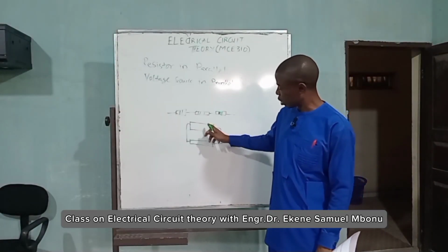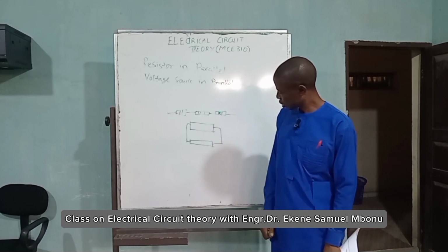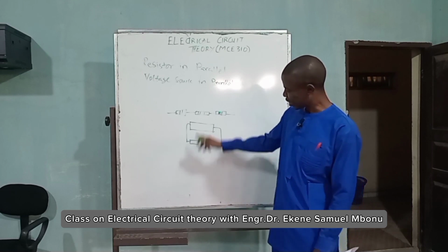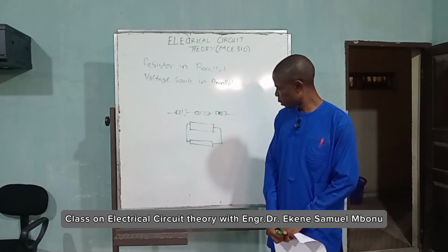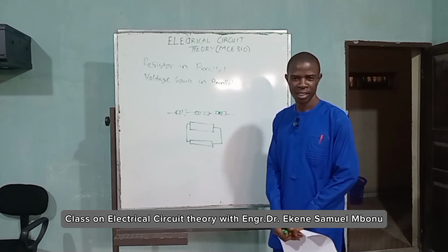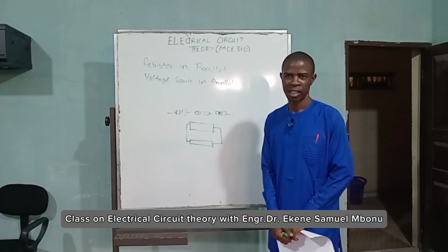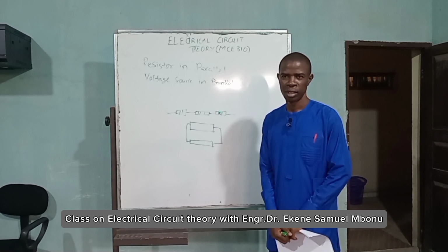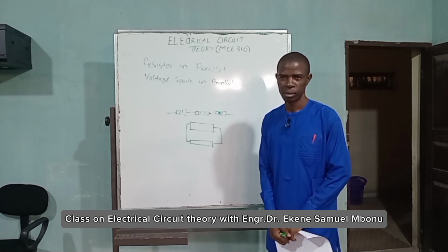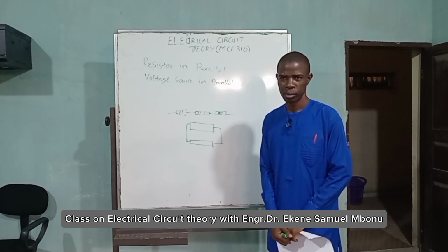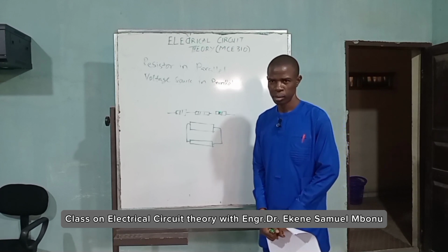Is this one in parallel, right? This one is in series. Why do you say this one is in parallel? The circuits are said to be parallel because the resistors are connected parallel to each other. Each resistor is connected directly to the voltage source, not to one another. Because in a parallel connection, when the voltage comes, it splits and goes into each respective resistor. Whereas in series, the voltage passes through each resistor, dropping gradually through each resistor till it leaves the final.